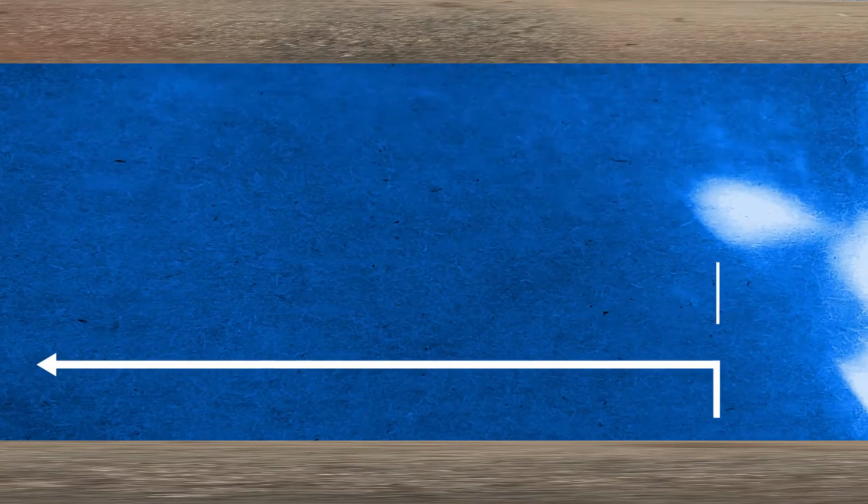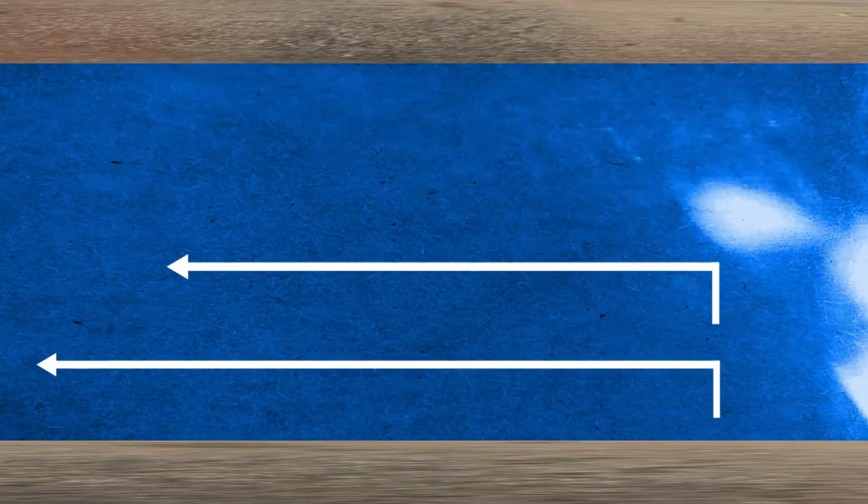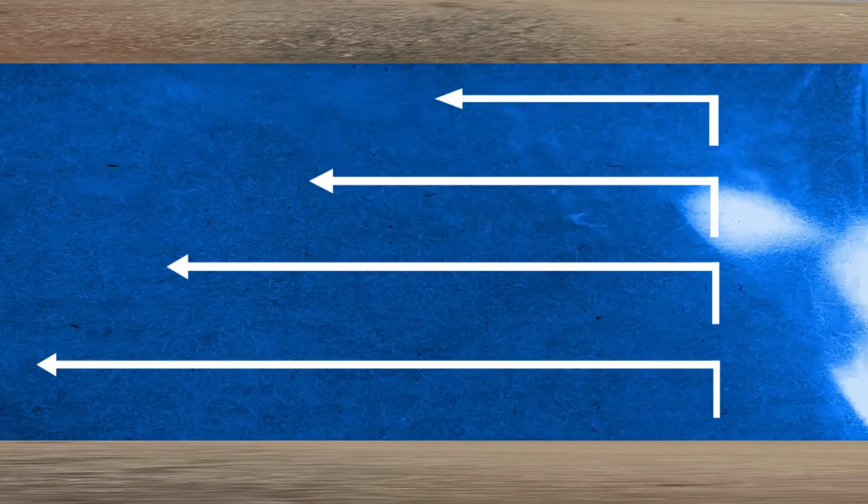We can interpret the flow between parallel plates as momentum transfer. The fluid in contact with a moving plate acquires a velocity and therefore momentum in the x direction. Some of the momentum is transferred to the adjacent layer of fluid above it, which is also set in motion in the x direction. Each successive layer of fluid is dragged along by the viscosity.